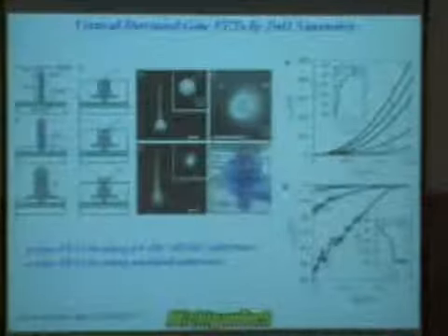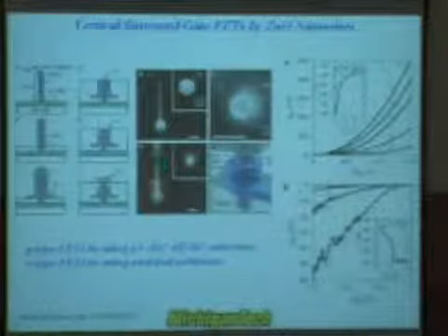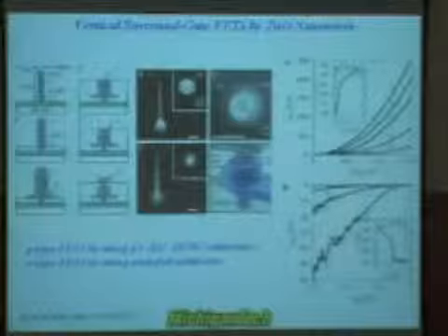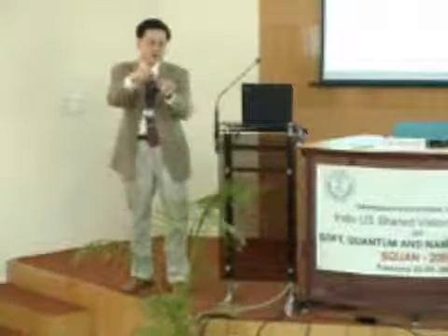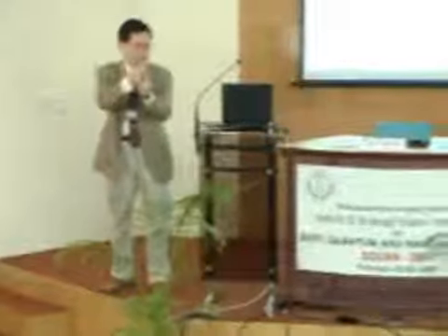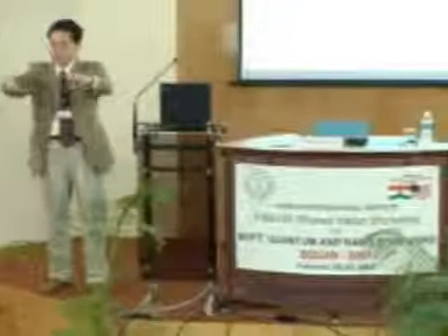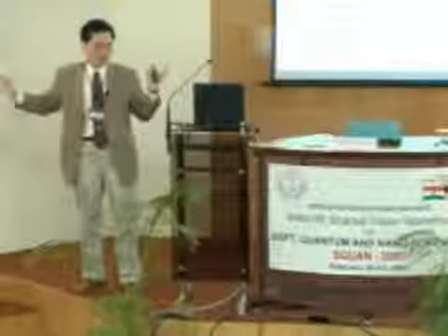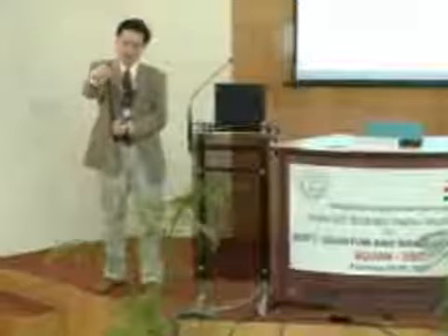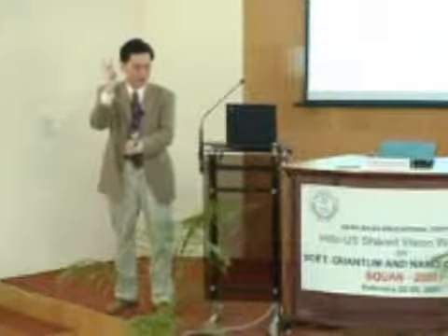And more fascinating here is that you can make them grow vertically aligned like this. If you have a substrate and you want to lay your one-dimensional materials horizontally on the substrate, you need to put electrodes in this way. Even though your nanotubes or nanowire is a few tens of nanometers in diameter, the actual area of the device that you can make will be micrometers. So you don't want to use them that way. Instead of putting them horizontally, you want to make them vertically. So materials that can grow vertically will have an advantage, right?